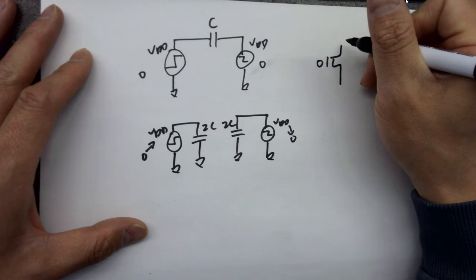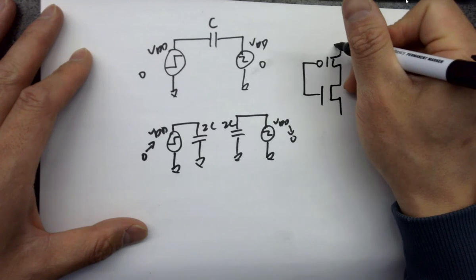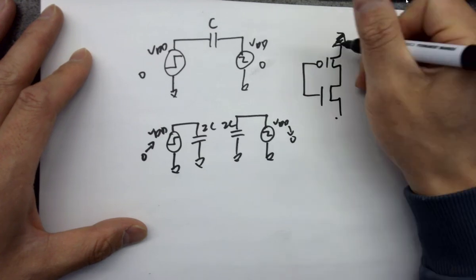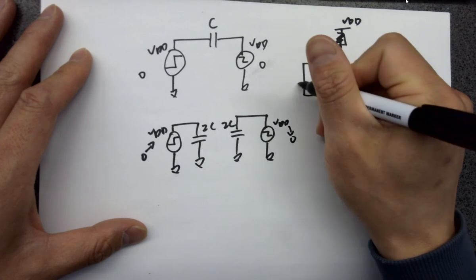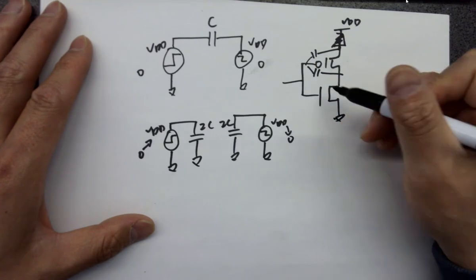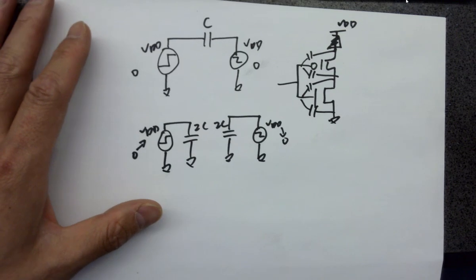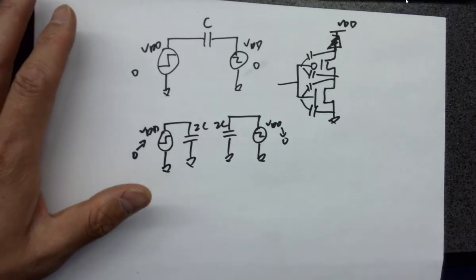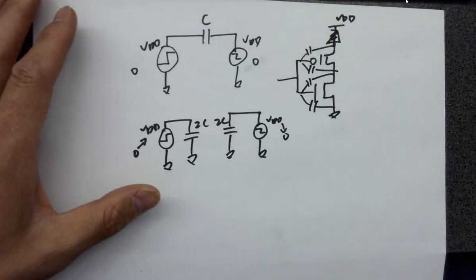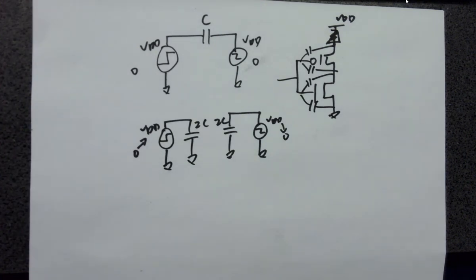And so by looking at the transistors, especially the inverter, VDD, it has all these caps. It's because of the gate oxide. So caps like this is how we model it. And you have to be able to identify which capacitors have Miller effect. Miller effect means the actual input capacitance is bigger than its physical capacitance.